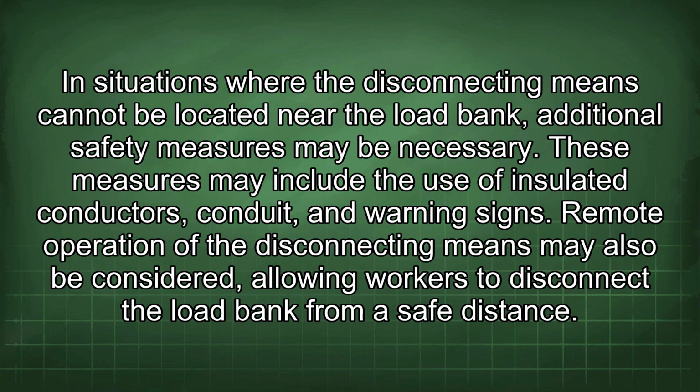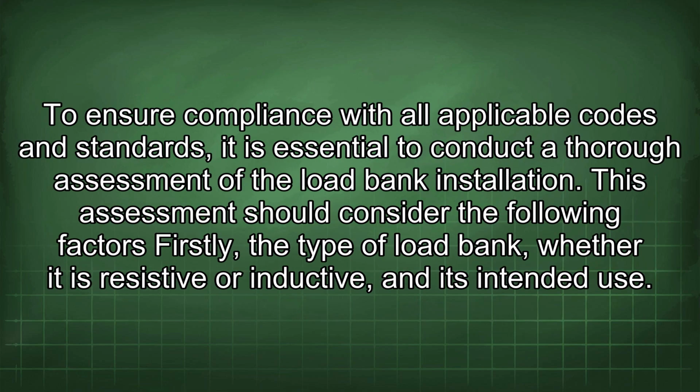These measures may include the use of insulated conductors, conduit, and warning signs. Remote operation of the disconnecting means may also be considered, allowing workers to disconnect the load bank from a safe distance. To ensure compliance with all applicable codes and standards, it is essential to conduct a thorough assessment of the load bank installation. This assessment should consider the following factors.